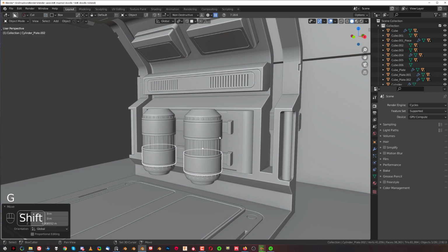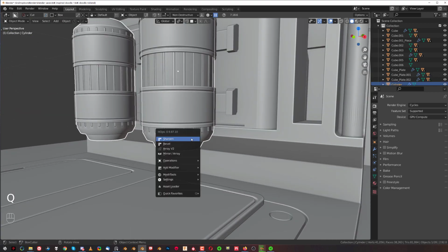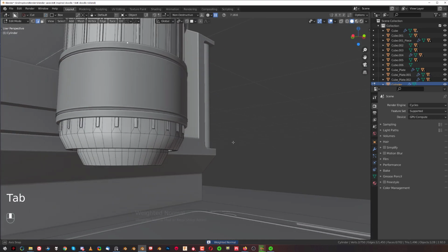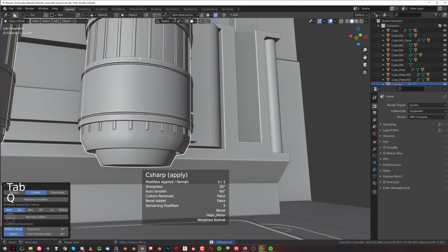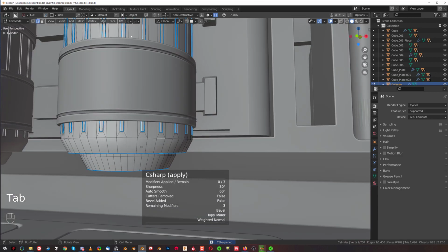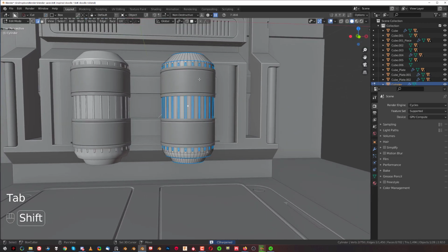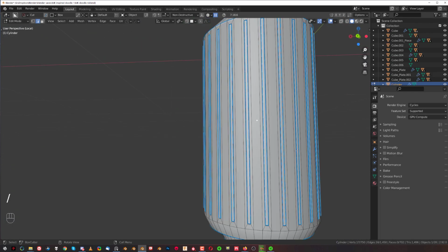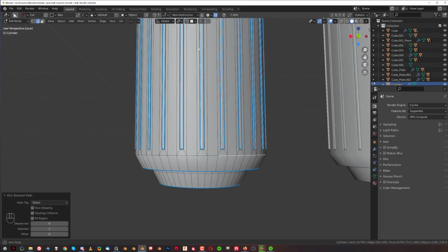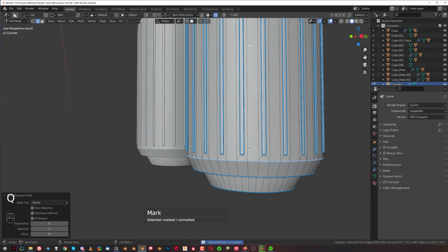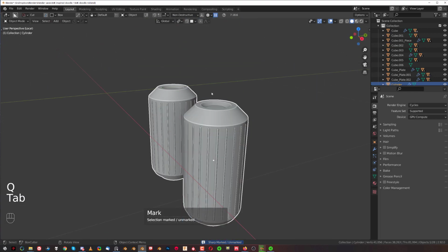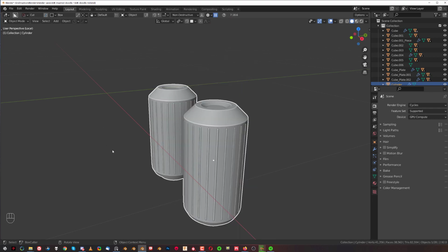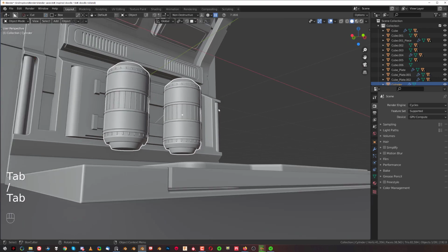HardOPs and Boxcutter. If you duplicate a mesh with booleans, it's going to run it with a parent, so the cutter is going to get parented and copied at the same time. Let's switch here bevel to weight, so you're going to catch this bottom edge. It's going to look a bit more sharp and defined.